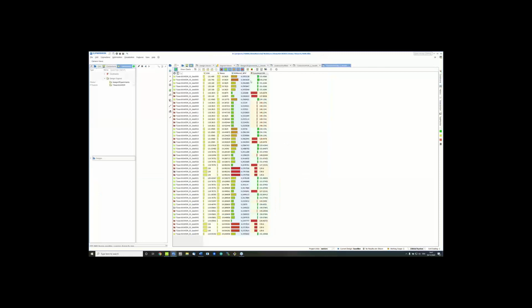We can, of course, then do the same from the other variant. From those cluster of points, we can choose the slightly narrower but longer vessel and run another optimization. And I've done that prior to this presentation. You can see here that from the initial NPV of 0.255, we can actually converge down to an optimized variant of 0.237. And again, if we verify that in CADMATIC, we'll find that there's actually an improvement in objective function of 15%, which translates into an improvement in NPV of 4%, which in turn translates into real money savings.